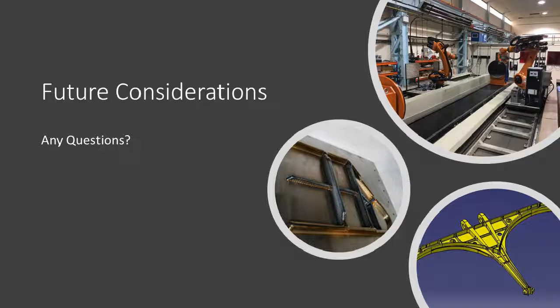Great, and we've got another question, which is, what is the consistency of quality across a batch of identical parts? Okay, again, it depends on the techniques being used. So in investment casting, which we looked at for this, probably 1 in 5 parts could have a defect or a flaw. It depends on the cross-section of the part you're printing. But that's mostly errors that have come in from the casting process rather than the 3D printing process. In 3D printing, it depends how you print, because if you print a batch up as one go, as one run of the printer, then you should have a very low rejection rate.